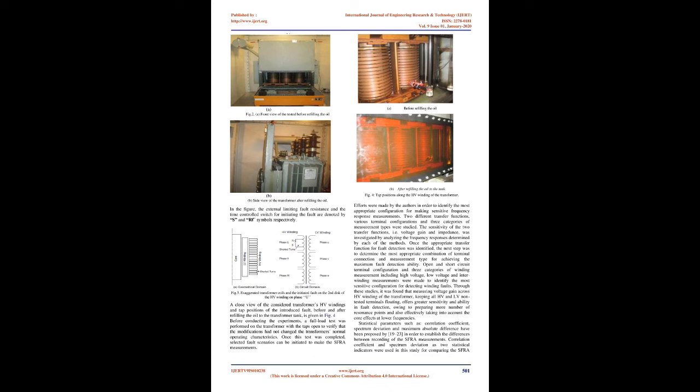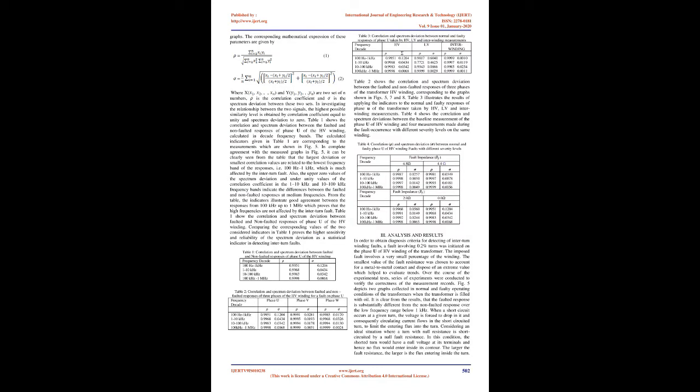After reassembling of the transformer, inter-turn faults could be initiated by connecting two taps to each other through a low-impedance knife switch to be able to handle the extremely high circulating fault currents flowing through the shorted turns. To adjust the fault severity in the shorted turns, a variable resistor was used in series with the switch in the conductive path between the terminals of the fault region. Various levels of fault severity can then be attained by changing the value of the fault resistance in this leakage path.